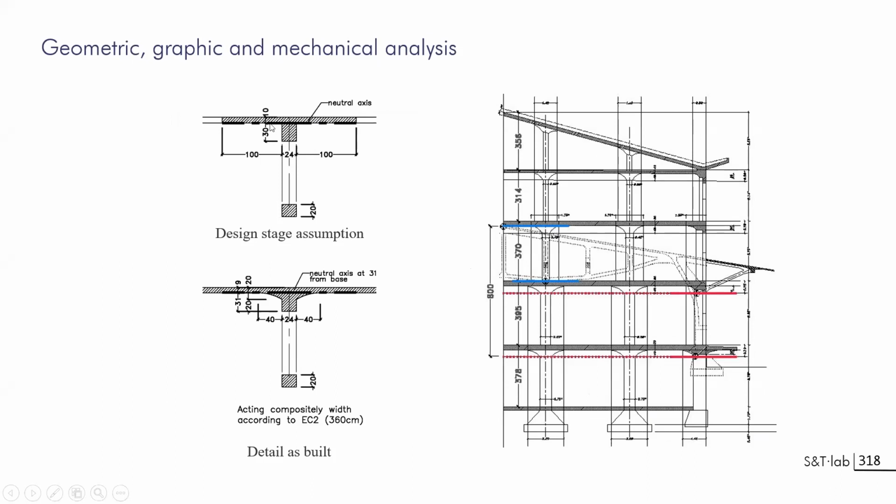You see that Maillart, with the first sketch, is using a very simple mechanism. You have a flange of 1 meter, you have a thickness of 10 centimeters, and you need a rib below of 24 centimeters on the horizontal line and 30 on the vertical line to get the neutral axis just at the limit of 10 centimeters. And you will have another line here, just a minimum of 20 centimeters to be able to have the tension reinforcement passing through it. At the end, you will have a kind of rounding, as Maillart does very frequently on each of the bridges, using a parabolic line, so you know how to draw a parabolic line, and to have a stiffening member.